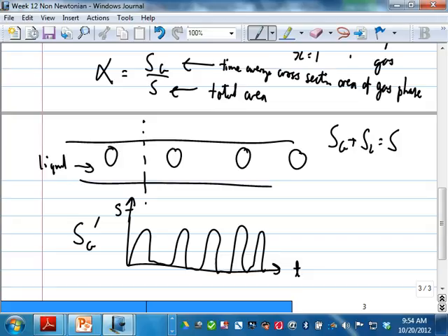If some of you ask how this can be measured, it depends. There are various ways to measure, because the gas and the liquid have different properties you can measure on. Sometimes you can use capacitance, inductance, resistance, or other electrical signals, because the electrical properties of liquid and gas are different, so you can use that. Sometimes you can do it optically, taking snapshots and then measuring. Or sometimes you can use ultrasound and so on. So there are a lot of different techniques to measure.